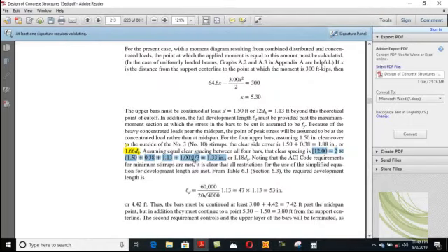So this calculation is basically 1.50 is the clear cover, 0.38 for the stirrup, 1.13 for, I think, the number 9 bar, and 1 for the number 8 bar, divided by 3, because there are 3 equal spans, 1.33. Your clear spacing, you can say, is 1.18 db. Okay, 1.18 db, and you have available 1.66 db.